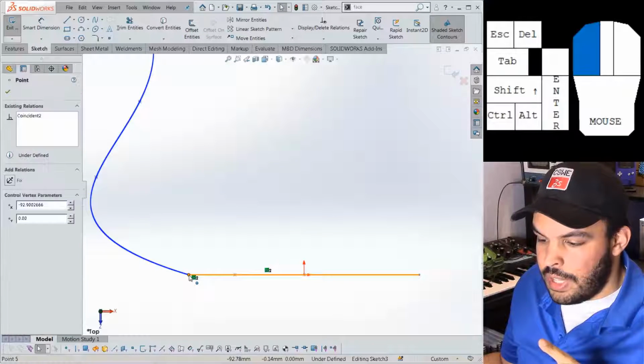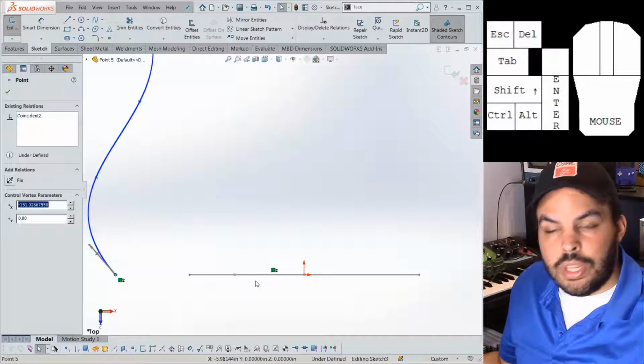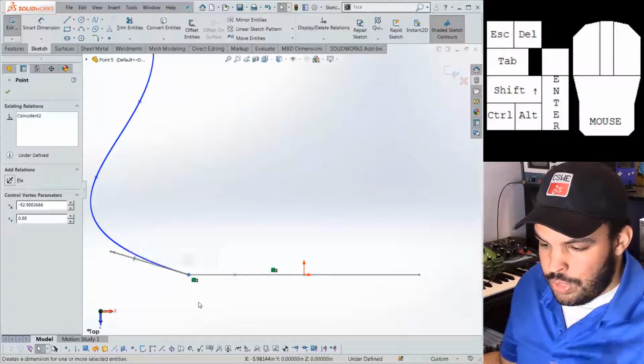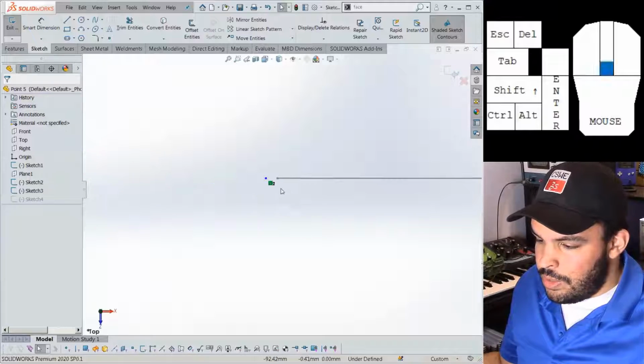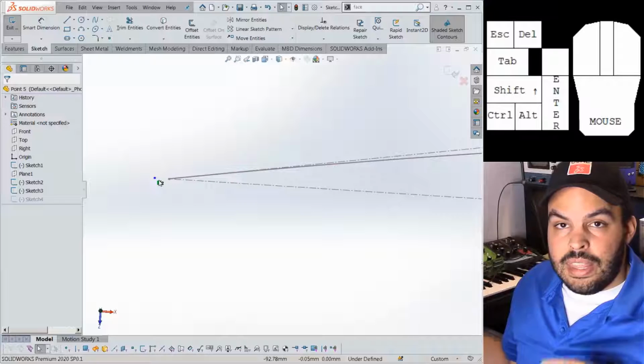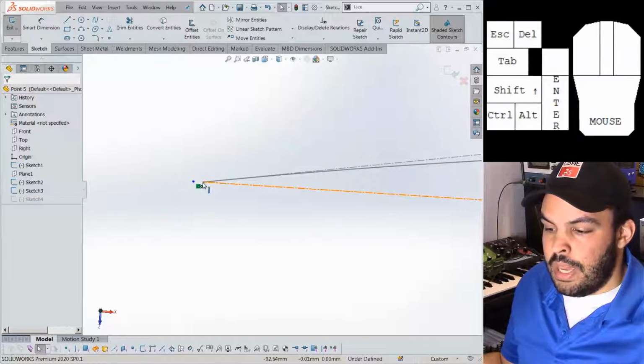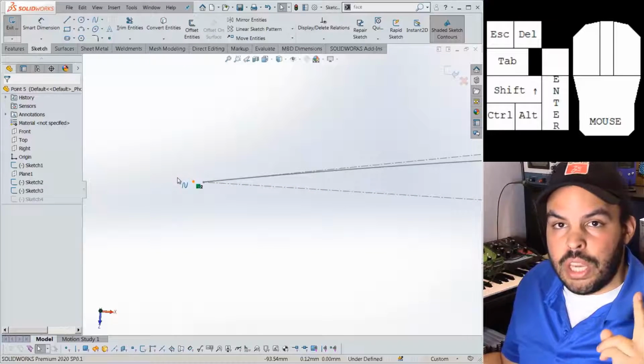So if I take this point and I move it away, you can see it was not constrained at all. And if I do Control Z to put it back where it was and zoom in really, really closely, there was a gap. And that means that at this point here, SolidWorks was trying to make a point of a surface be in two locations at once.